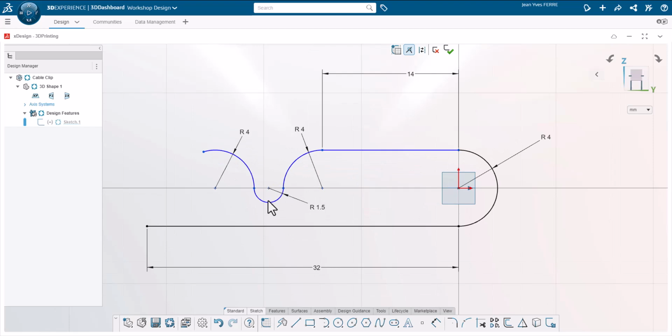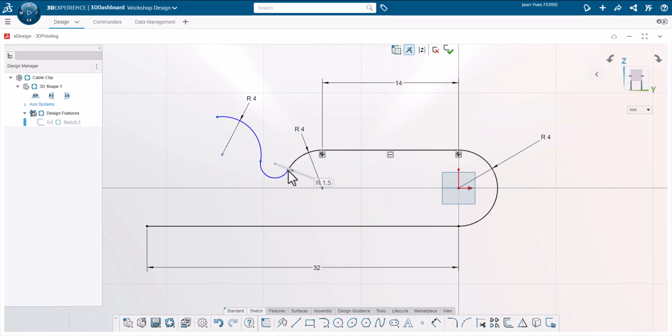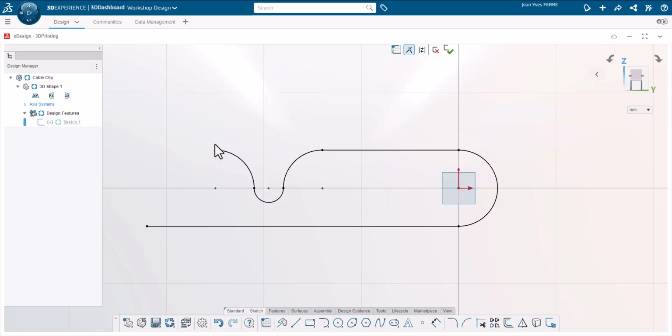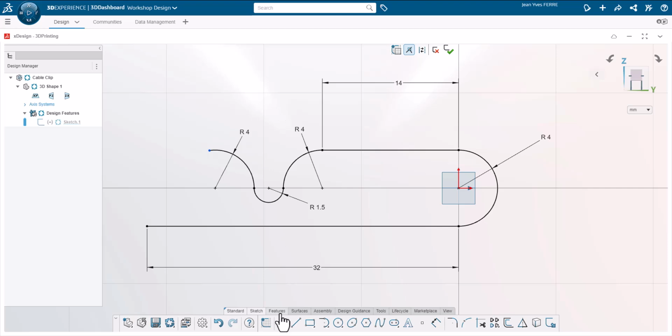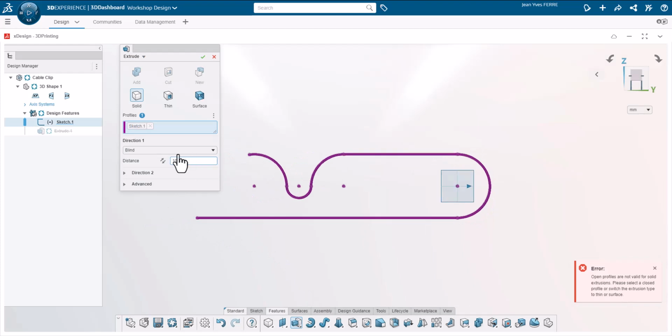Here we see this line needs to be forced horizontal. This arc needs to be horizontal too and measure 180 degrees. So I align those 3 points. As you can see, this is enough to turn sketch entities from blue to black. This means they are fully defined. We will take care of the last blue point at the last extremity later.